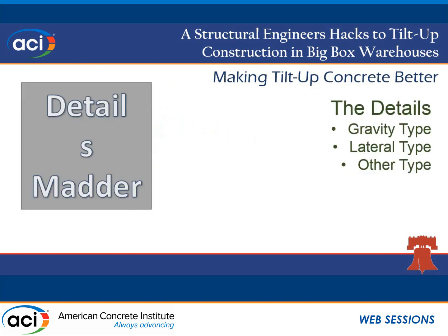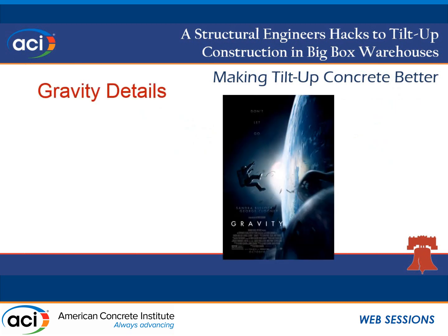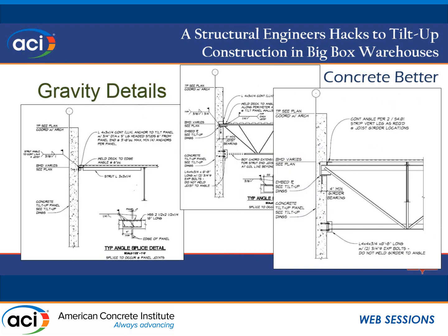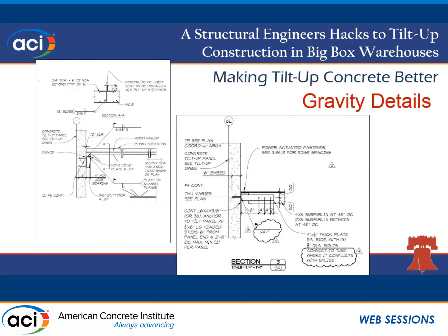A few details to run through real quick at the end of my presentation. Some gravity details. I love pockets. Pockets are great. Pockets are easy to construct. The only thing on pockets I would say is I always put the load at the face of the panel, because that's where I think the load's going to get into the panel.